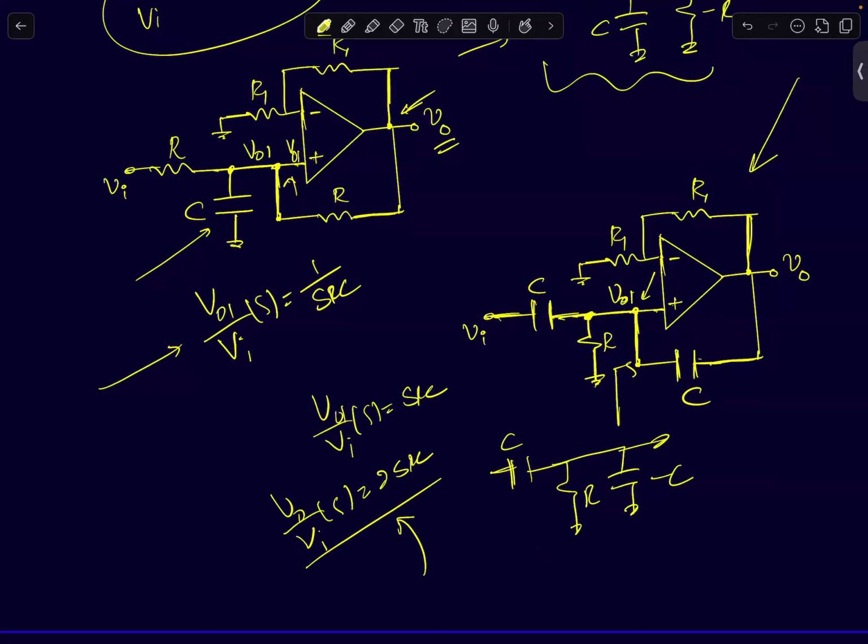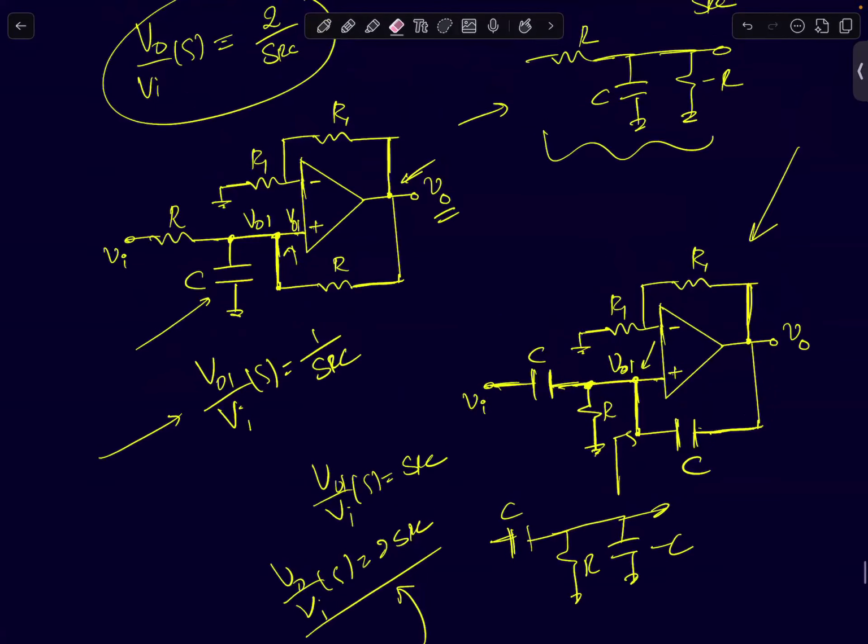Okay, so if you just directly stare at this circuit, you will immediately observe that it has 2 kinds of feedback in it. The voltage is fed back at the inverting terminal, and the voltage is also fed back at the non-inverting terminal. Okay. And so here, let me remove the confusion. The feedback resistors are R1 and R1. They don't have to be similar to R. They are just there to give me a gain of 2. That's it. This ratio of 2 resistors is within your control. You can choose these resistors to be independent of these 2 resistors here.